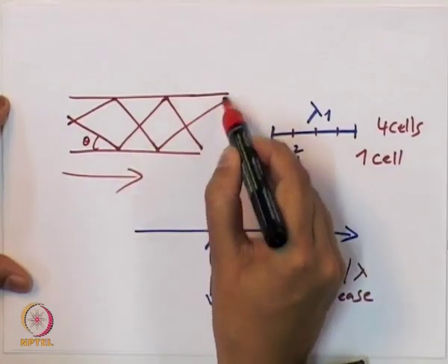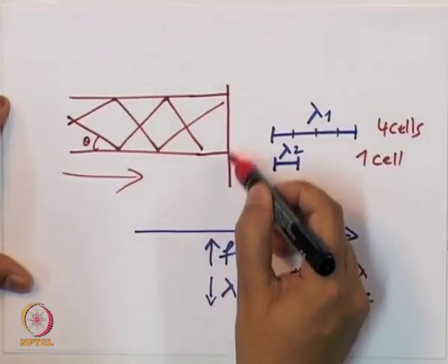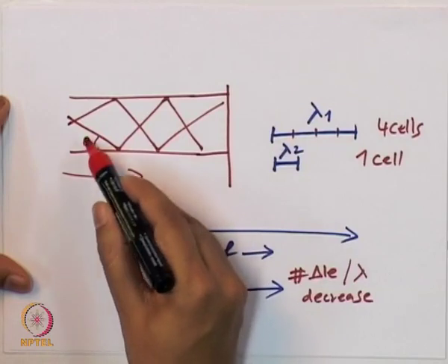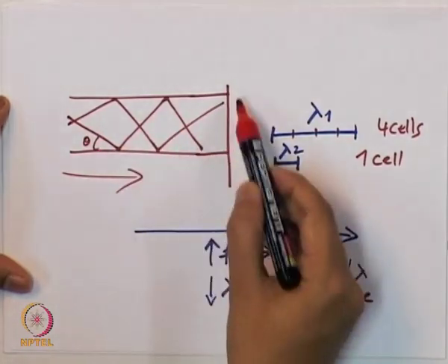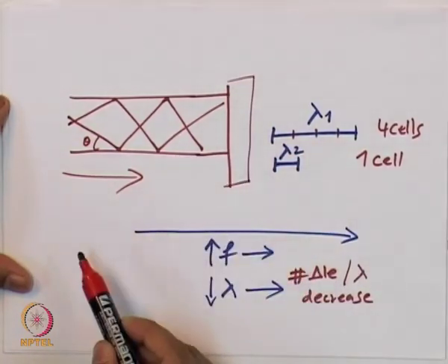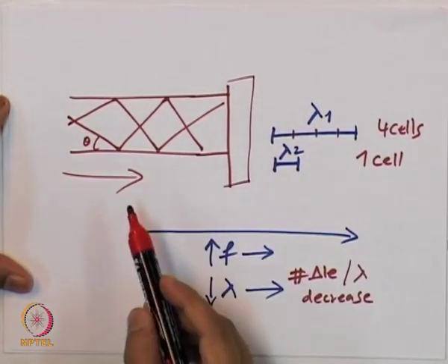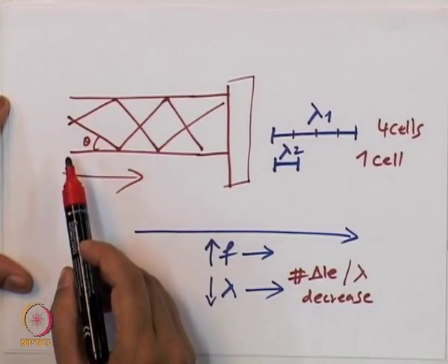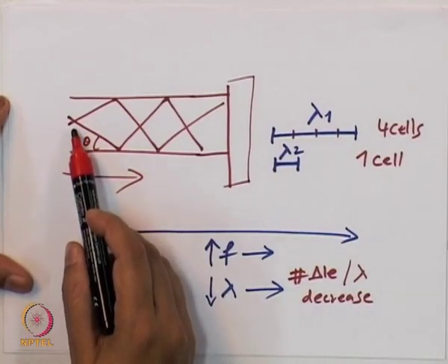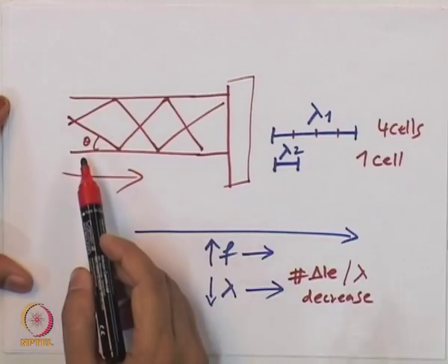So when you are computing what is happening here, this is the theta, the angle at which it is going to impinge on the PML layer. So here is where the PML is sitting. What we are talking about is, as we increase the frequency, we are coming closer and closer to normal incidence.